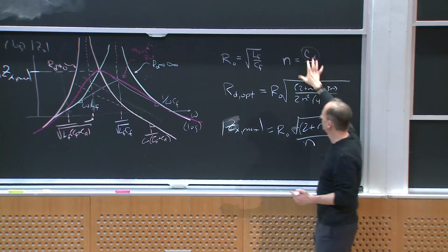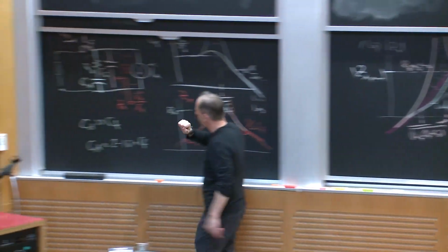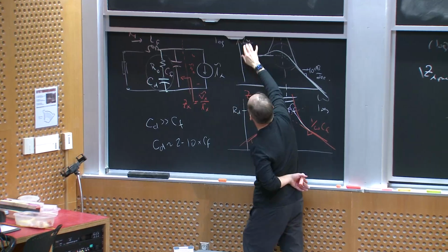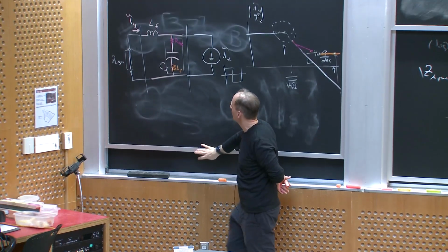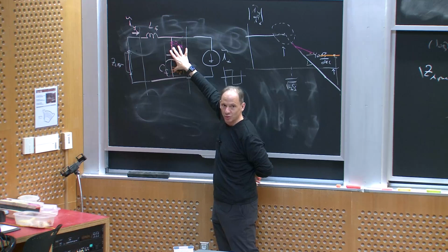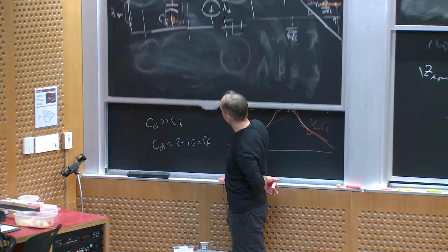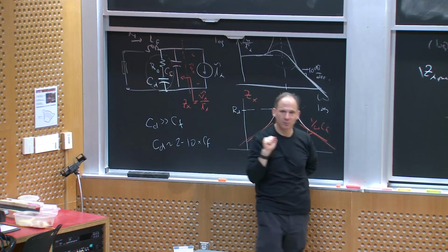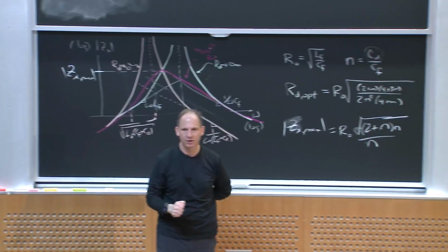On the other hand, CD and CF, if I come back to this original design, CF is important at the ripple frequency. We were talking about, up here, that I really care about the parasitics of this filter capacitor in order to get good high frequency attenuation. So CF's job, the filter capacitor job, is really to help me attenuate the high ripple frequencies. He wants to be a really good capacitor for high frequency.